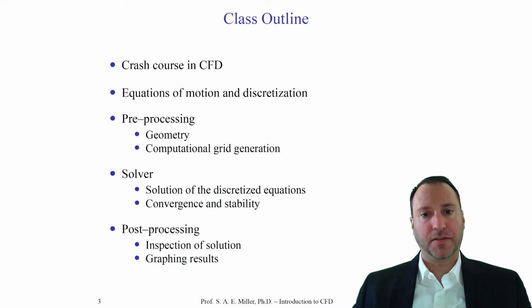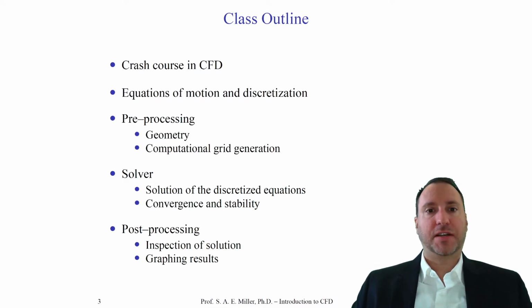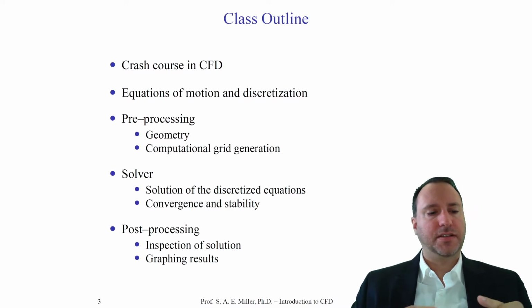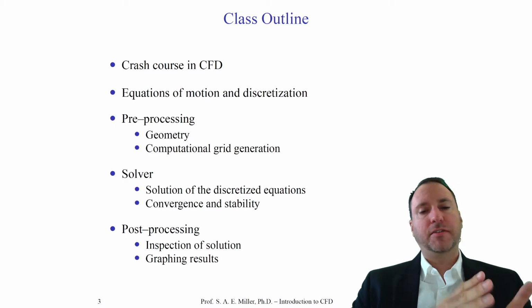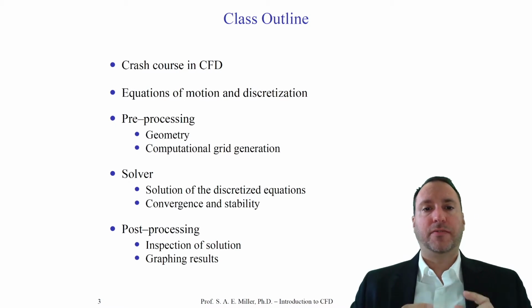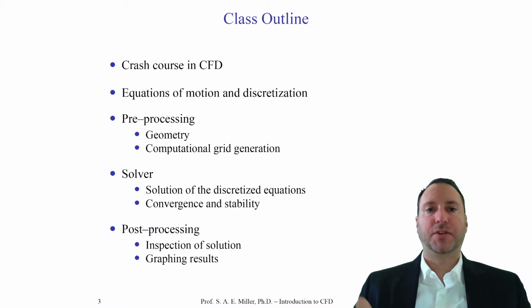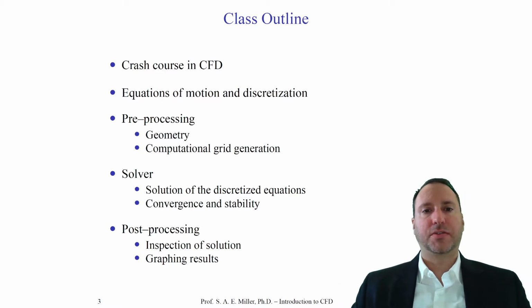For example, conservation of mass, momentum, and energy, and perhaps a gas law, and any other sets of equations or reductions of those equations you might look at. Discretization of the equations is how we take these equations written in the continuum domain, if you will, and convert them into a discrete form for discrete mathematics, which can be evaluated by computers. Because computers are digital, they are essentially doing and evaluating discrete mathematics for us in computational fluid dynamics.